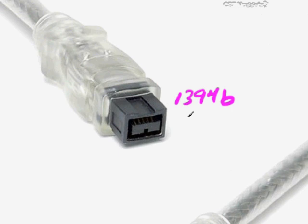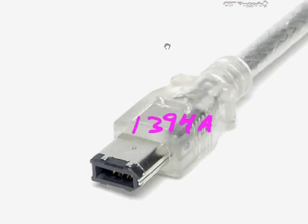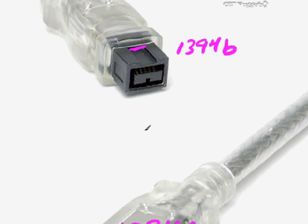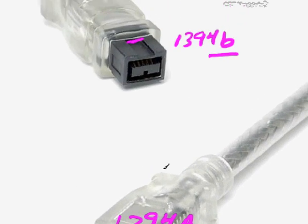This is a 1394B cable. And what we see with this one is it's known as a bilingual cable. It uses 9 total connectors on the top. I don't know if you can see them, kind of small there. But there's 5 connectors on the top, and underneath that you would be able to see 4 additional ones. And it has kind of a narrow notch up here at the top. The narrow notch designates this as bilingual, which means that you can connect this to the device, whatever you're trying to work with, and the other end into your PC, and you can work with a 1394B device connected to a 1394A port, and that should work just fine.